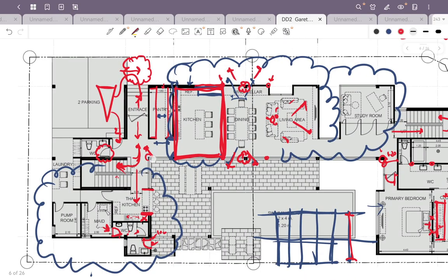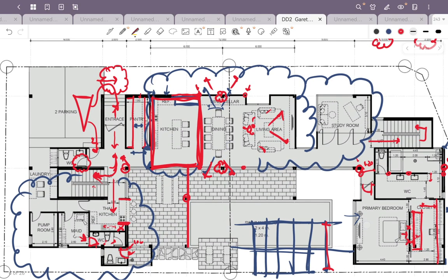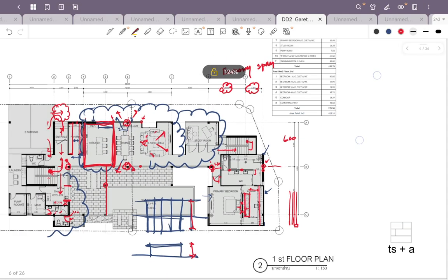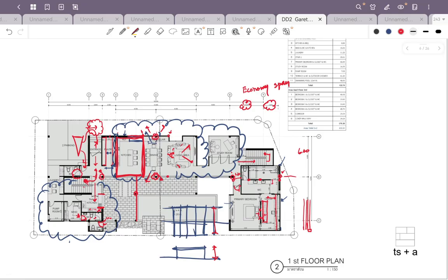And then you look at the grid line. You have a grid line for the beam here, and then suddenly it's missing, and then they change the grid line to be here with no reason. So for me, what can I say, okay, that is my opinion on your layout plan. Roughly, if we still need to follow this one, these are the things that you should be concerned about and make them revise.